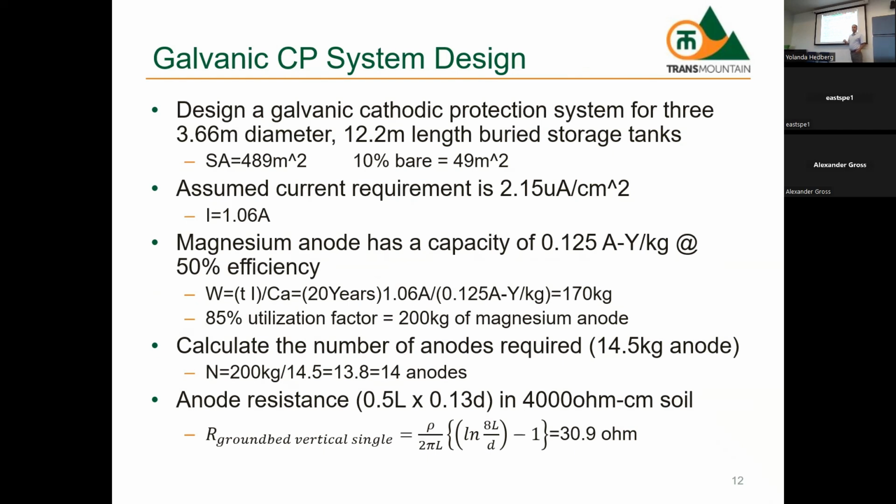In an impressed current system, you have multiple anodes to produce your current. Well, Dwight's formula has another portion in here when you start introducing multiple anodes to calculate an overall ground bed resistance. So you have what's called a spacing factor. And that's if I put one vertical here and I put another anode here, 1 meter apart, the spacing is 1 meter. So that gets put into the formula. The further away I get with them, there's no mutual interference between the two anodes, which diminishes the effect of having multiple anodes.